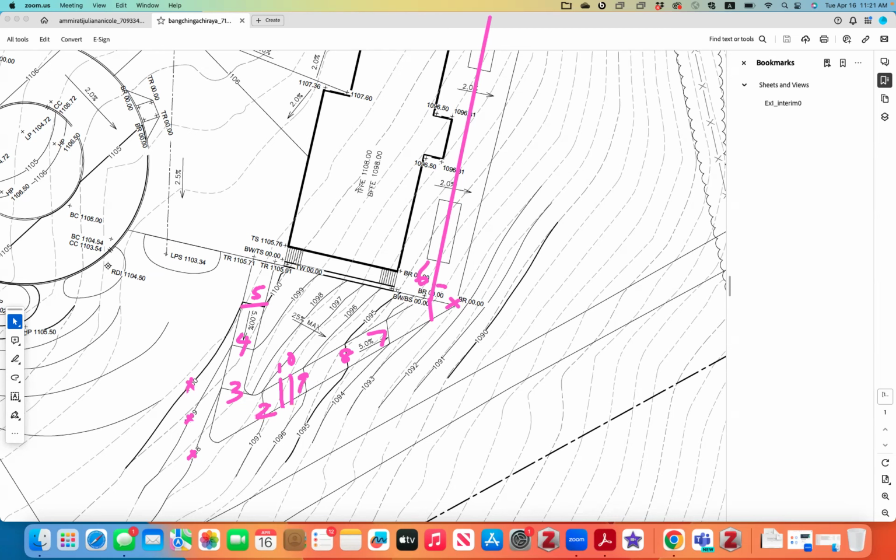I would actually fix the top FFE and the bottom FFE first, and figure out where 96 is. You know what, 96 is very likely going to take this form. Okay, this should be the contour form of 96, and then you go up. And basically now you know how long you need the ramp to be, right? And then you could start revising the shape of it. All right, but these contours are connected pretty well there, right?